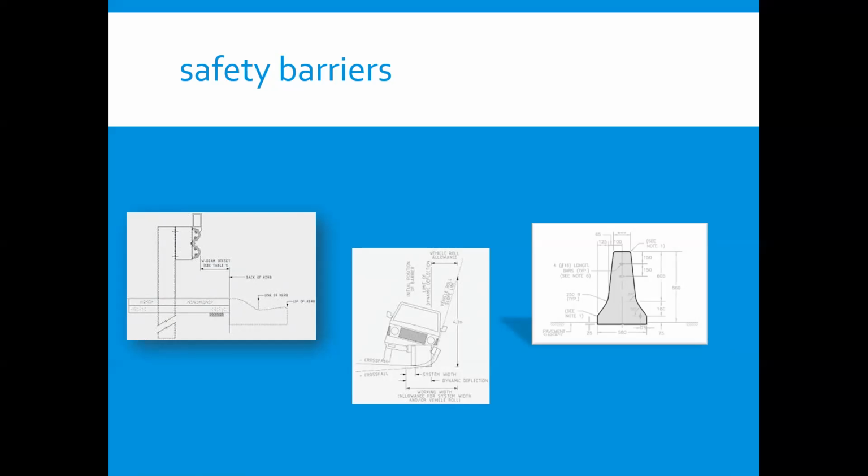Available options are using a steel guardrail terminal assembly to protect the end of the concrete barrier in association with a bridge approach assembly, or protecting the barrier with an impact attenuator or crash cushion system. Site characteristics will determine the most appropriate type of attenuation to be used. Concrete safety barriers should be considered on high volume major urban roads as they retain full functionality after impact, provide excellent whole of life cost, and minimize the risk to maintenance workers as maintenance is minimal after impact.